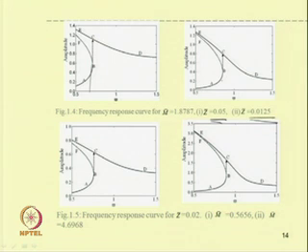So, one can have this jump up phenomenon, or the system will become stable up to a higher value of omega. Similarly, by changing the mass ratio, one can observe that for a lower value of mass ratio, the jump up phenomenon at point B takes place at a lower value than by taking a higher mass ratio. So, here m bar equal to 4.69.